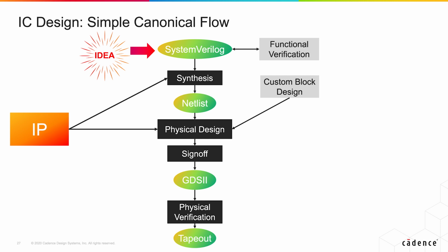It doesn't build the chip itself, it builds the design for the whole chip. The rest of the process is to check that the whole building the whole chip thing worked fine. There's a thing called sign-off, which checks the timing and the power, and then we end up with the layout in a form that we can send off to the foundry to be manufactured.